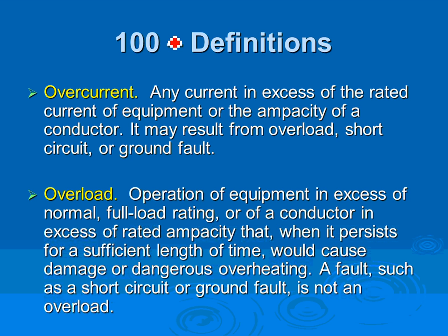Okay, there's overcurrent and overload, and I can't get my students to know the difference between them all the time. You get them confused. Overcurrent, guys, condition can be an overload, a short circuit, or a ground fault. If you hear the word overcurrent, you can have an overcurrent condition because of overload, or ground fault, or short circuit.